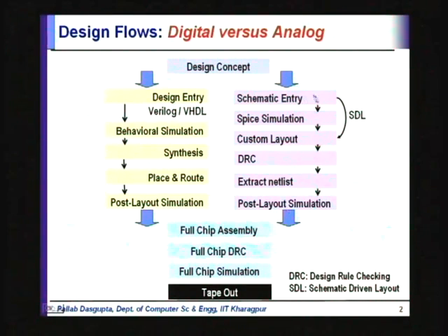Now, in this space a lot of new things are beginning to happen. This space between the schematic entry, spice simulation and custom layout. What is happening here is that we are bringing in behavioral modeling, where instead of entering the schematic directly, we first create behavioral models of the blocks, okay, make sure that those models together are implementing the design intent correctly, and then build the different blocks.